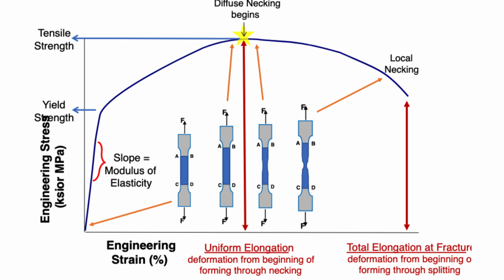The polymer, however, differs dramatically from ductile metal in that the neck does not continue shrinking until the specimen fails. Rather, the material in the neck stretches only to a natural draw ratio, which is a function of temperature and specimen processing, beyond which the material in the neck stops stretching and new material at the neck shoulders necks down. The neck then propagates until it spans the full gauge length of the specimen, a process called drawing.